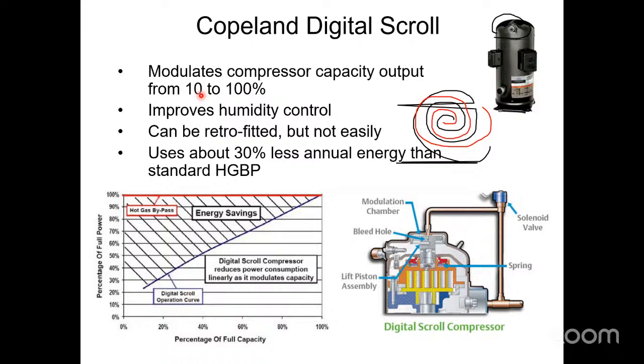Things are better. Sound blankets have helped, etc. But it's not as quiet as an inverter. So that's the knock on it. So it's better control, but it's not quite as quiet. This saves energy compared to hot gas bypass. Hot gas bypass just saves no energy at all, like zero energy savings on hot gas bypass.